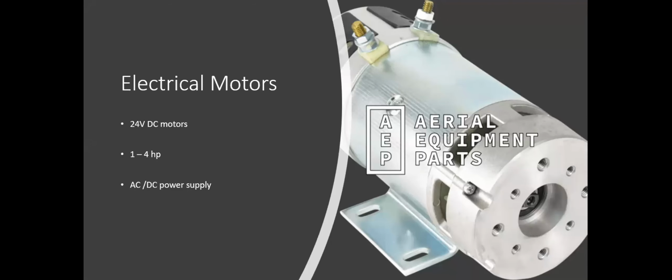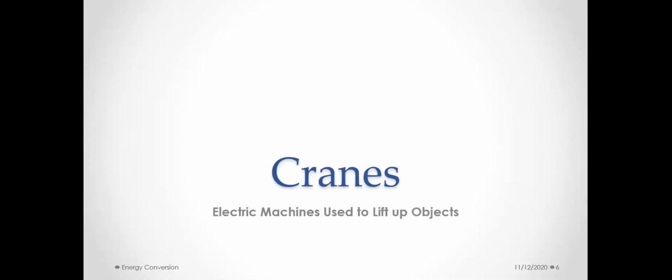Now, the motors used in these lifts provide more reliability than their fuel-powered alternatives, and significantly less maintenance. The particular motor shown here is a 24-volt, 4-horsepower flex-coupled DC motor. This is a typical motor, as they usually use a 24-volt DC motor, and they range from 1 to 4 horsepower. And they can run off of either a rechargeable DC battery pack or an AC power supply with an onboard rectifier. Now I'll hand it over to Josue next for our next section.